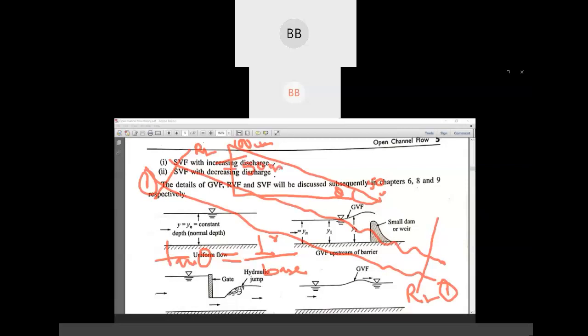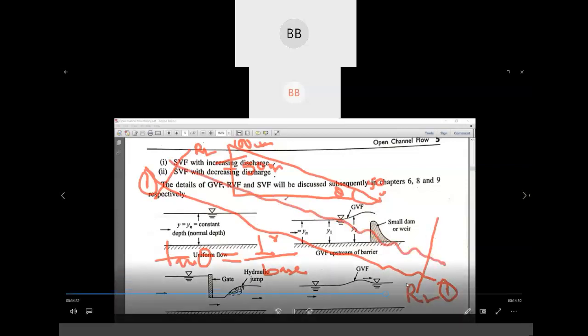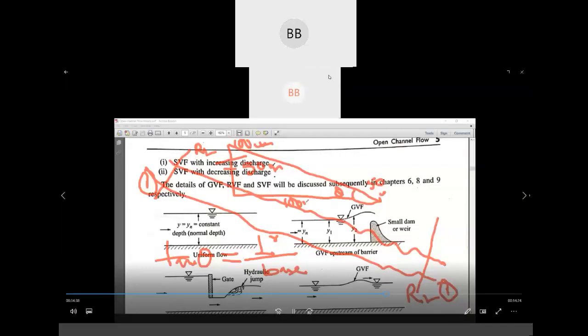Understood, na, Stephanie? Yes, sir. Then we are going to measure this distance from section 1 and section 2. What is the particular distance? And we consider it as a base. Suppose 100 meter. Then when you find out the slope, that is tan theta, it will be 50 by 100. That will give you the approximate slope of that particular channel.